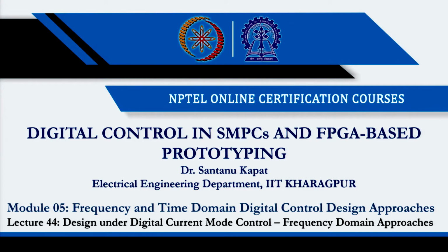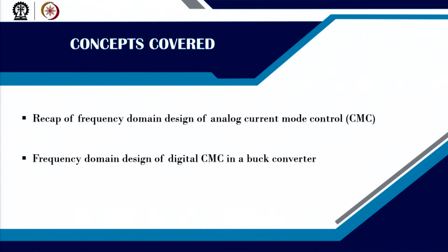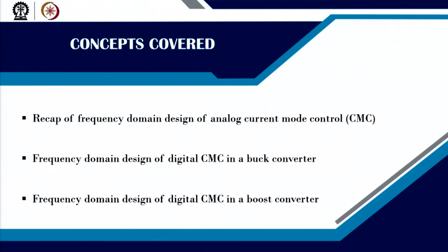So in this class we are going to talk about the design of digital current mode control using frequency domain approach. Here we will recapitulate the frequency domain design of analog current mode control, then we will discuss frequency domain design of digital current mode control in a buck converter, and then frequency domain design of digital current mode control in a boost converter.